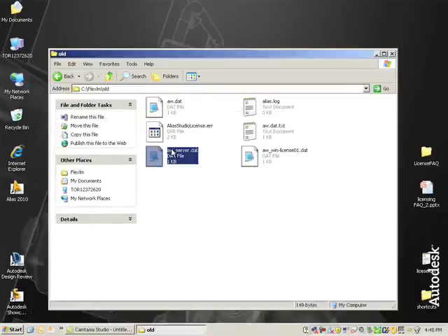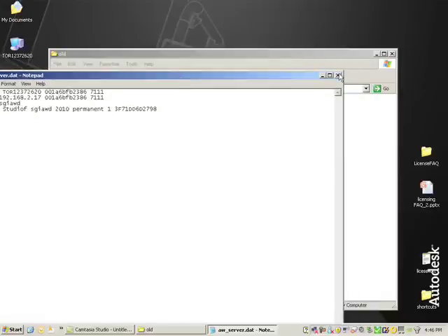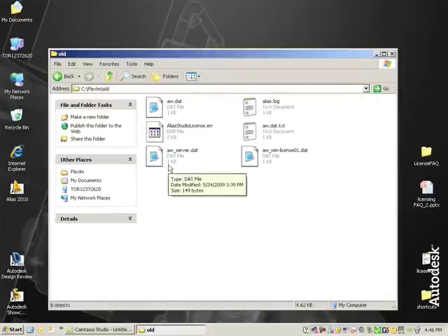I have my old server license here, so this is server license, and I would comment this one out and get rid of the comment. Save. Now on the server, what you would need to do is stop the server, restart, reread the license file, make sure the server is running, and then go to your client and just verify that everything is okay there as well.